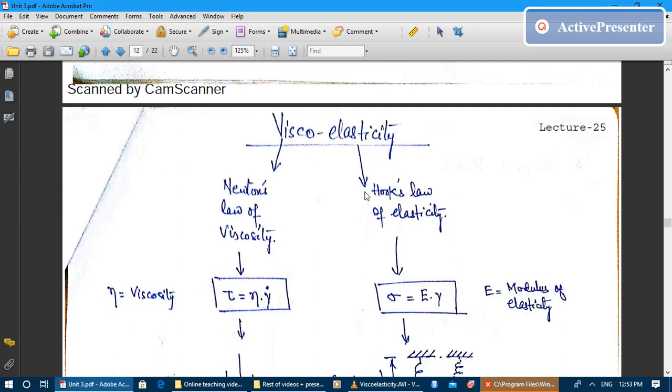You know, the primary bonds are much stronger than secondary bonds, because the bond energy for the primary bond is of the order of 80 to 90 or sometimes 100 or more than 100 kilojoules per mole, depending upon the types of bond, whether it's carbon-carbon single bond or carbon-carbon double bond or carbon-carbon triple bond. So it is in the range of almost 90 to 100 kilojoules per mole, whereas the secondary bonding, which is responsible for the viscous behavior of the polymer, is of the order of a few kilojoules. You can say from 2 to 3, 4 kilojoules per mole is the bond energy.